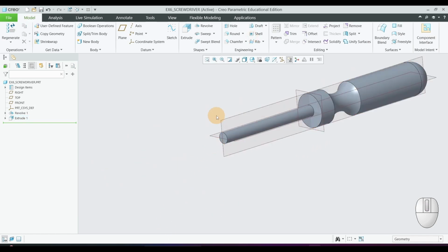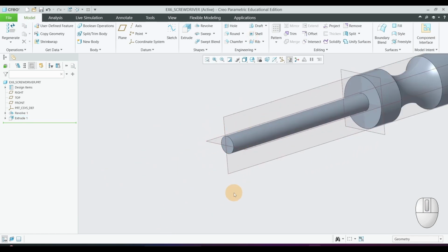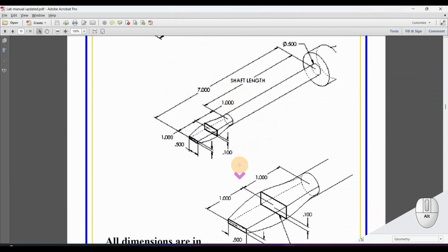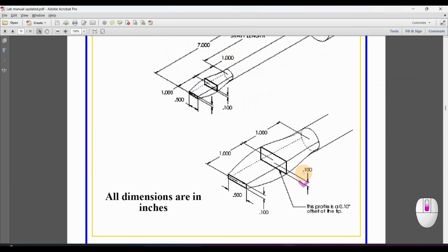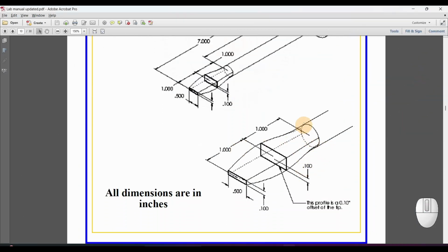The next step is we are going for a blend option and we are going to model it. To model this in blend, you can see that there is a circle and 2 rectangles. The largest number of points is in the rectangle, which has 4 points. The circle has only 1 point. So before we create a circle, I have to create it as a 4 point. Then we are going to connect it with respect to that.